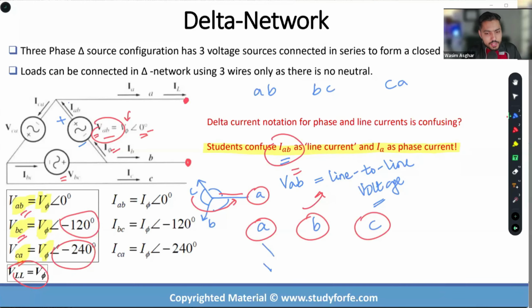So whenever we are calculating the line-to-line voltages, this basically means that it will be VA minus VB. The difference between them is going to be the first voltage that appears and then the second voltage that appears. So this is going to result in VAB. And then if I am calculating the difference in the line-to-line voltage between phase B and phase C, B appears first, and then phase C appears. So this basically becomes VB minus VC, which is VBC.